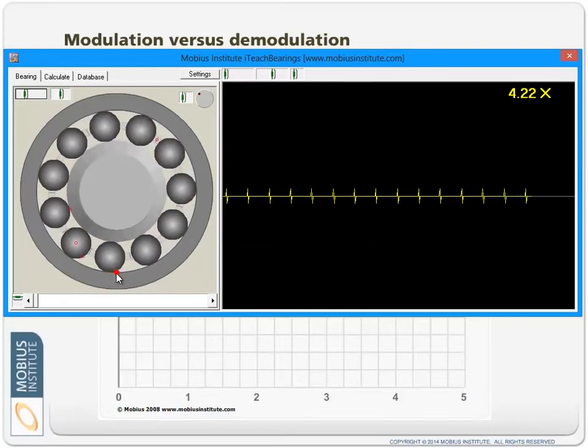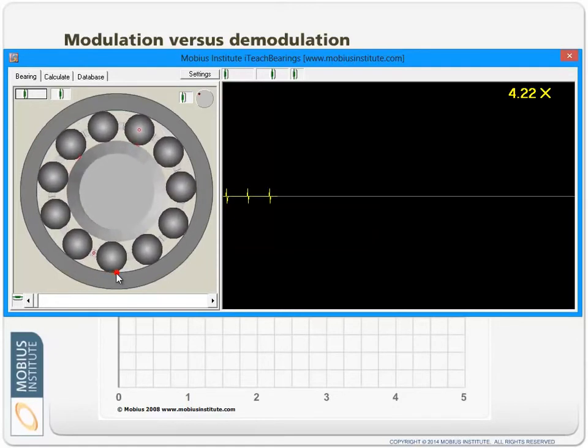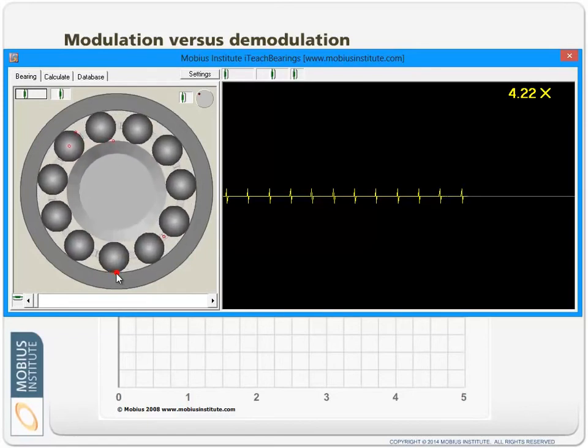However, if that bell rings at a high enough frequency, we can filter out all the vibration at a lower frequency than the ringing of the bell. So all that high amplitude noise and vibration that's distracting us from our analysis of the bearing or the bell, and all we can hear then is not so much the tapping of the bell but the ringing of the bell, or the stress wave that I mentioned. So now we see stress wave, or the bell ringing.